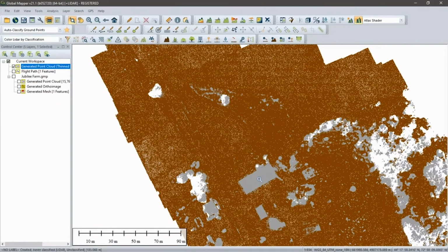You'll see where it's eliminated the buildings and the vegetation. We had a question earlier about this: how do we remove trees? This is how you would do that. Those points that are unclassified are no longer recognized as ground. If my intention is to create a DTM, I now have the raw material to do that.